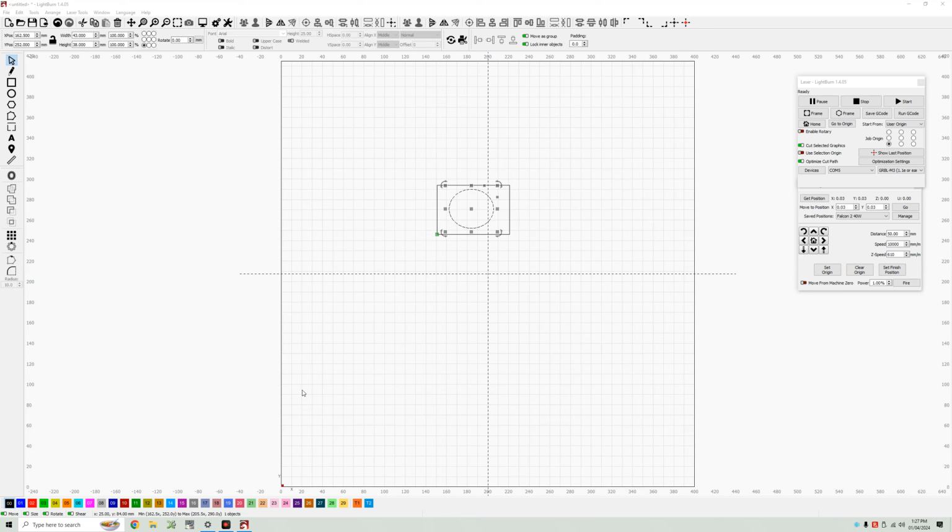Okay, so I made the portable laser workstation, and it was referenced to basically your home point. On the machines that I have, it actually coincides, but there's a little bit of inaccuracy in the little, literally 10-cent micro switches I use for homing. They have little springy tabs on them. Anyway, it goes down, it hits those things, it says okay, that's 0, it pulls off. They have a set 5 millimeter pull off, and then it says okay, that's your origin, and then in absolute coordinates it references off of that. That's the red dot.